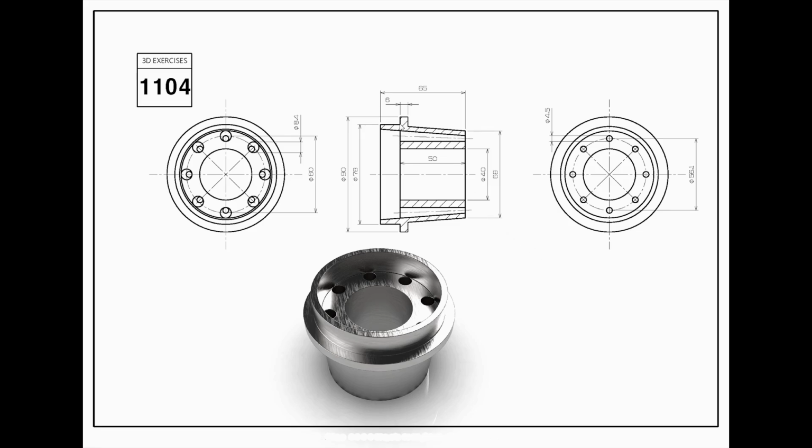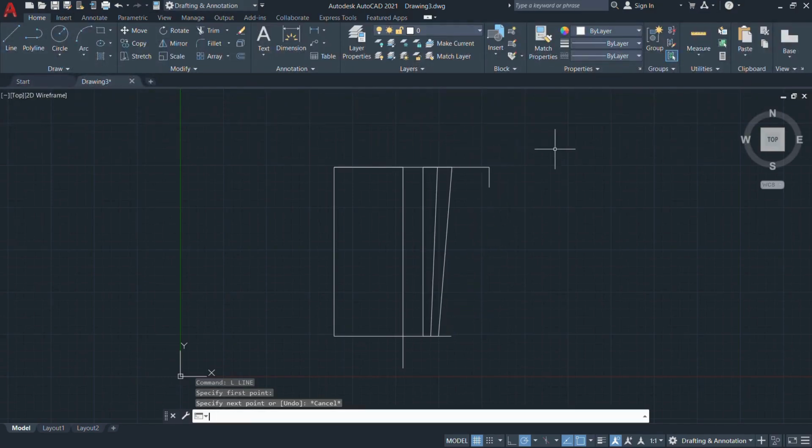Look at these portions. Here we need a reference before drawing our line profile. So choose a line and start from the top endpoint. Half of the overall diameter of 78 mm is 39 mm. Once we mention 39 mm, the profile is placed, and we connect the two opposite endpoints. Afterwards, draw one horizontal line.